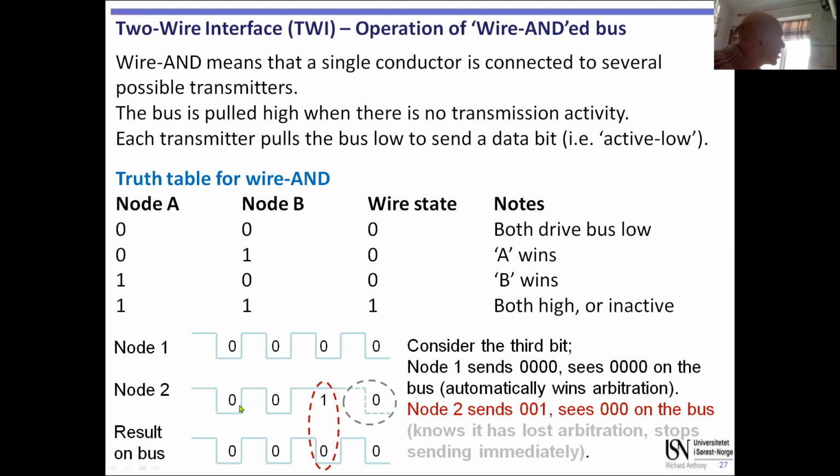And if they're both transmitting the same value at the same time, by the way, there's no data loss. Because here we had 2 signals on the bus, and the node that won, its data was not corrupted. The one that lost arbitration, its data was corrupted on the bus. Its signal was lost essentially, but it doesn't matter, because once it realizes it's lost arbitration, it will eventually start later on, when this one stops transmitting. This one will see a stop signal, so it can now start transmitting, and of course it will start its data again. So the data is not really lost, it's just delayed. Okay, that will transmit its data later on.